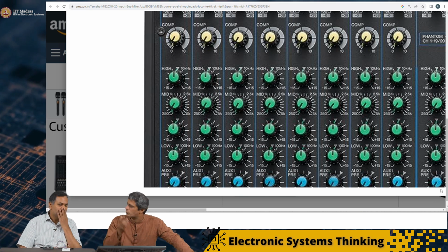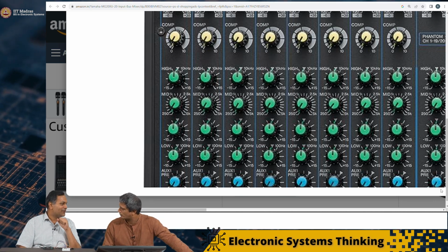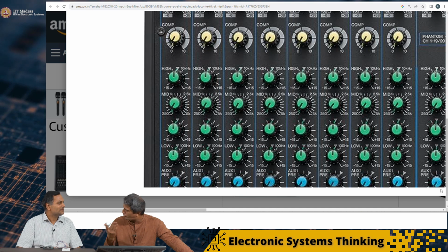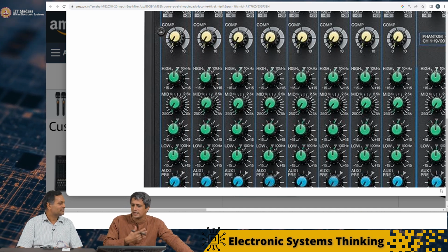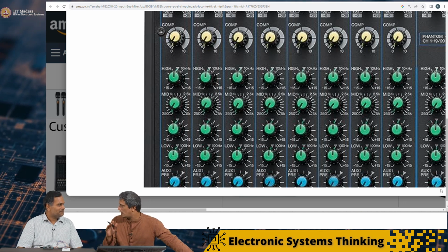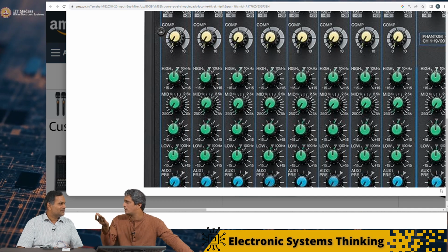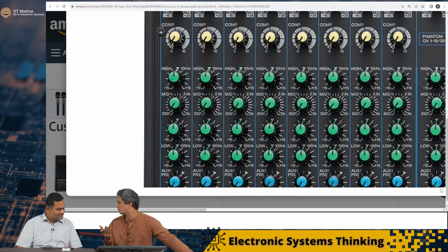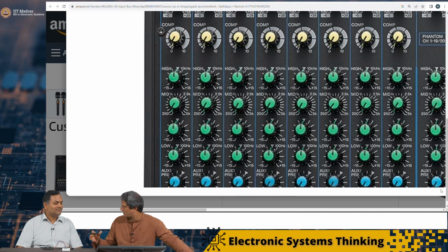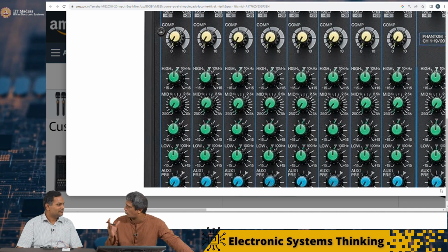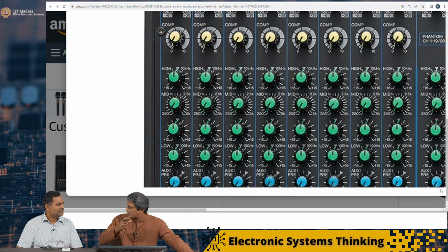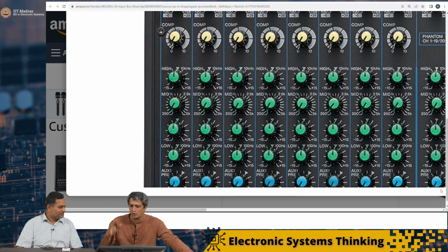So what's your guess? What do you think this would translate to inside a mixer? I think it's connected with what we have been learning so far in the last few classes. Most likely it refers to the frequencies and the filters. If you're talking about 10 kilohertz, we're talking about amplifying not the entire signal, but only frequencies above a certain threshold or below a certain threshold. So the low corresponds to some sort of low pass filter, amplifying frequencies around and below 100 hertz. 10 kilohertz, it says high, is probably some high pass filter around and above 10 kilohertz.